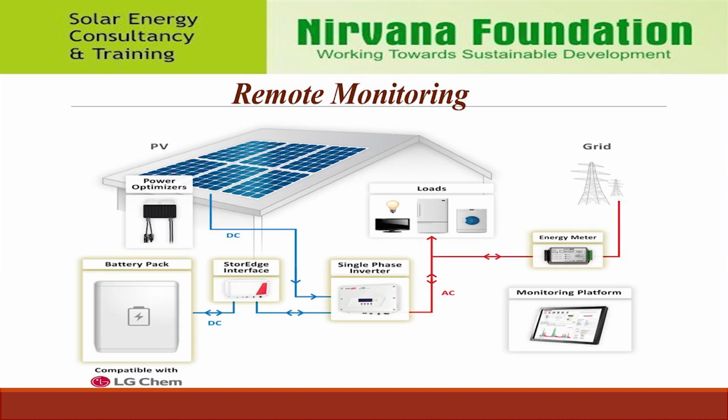Remote monitoring. The health of the solar PV systems should be monitored continuously for better performance and maintenance. For PV systems installed at rural locations, remote monitoring capabilities provide the information in advance when system performance is degraded or is likely to fail. Based on this information, preventive maintenance can be carried out to improve the performance and life of the system, thereby reducing the overall operating cost.